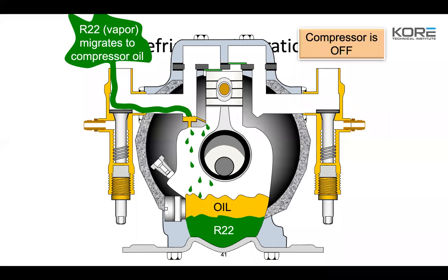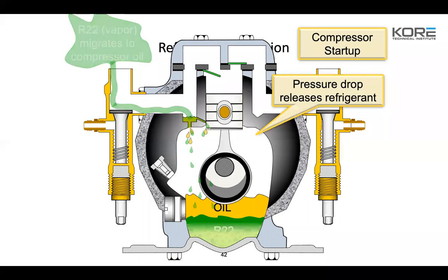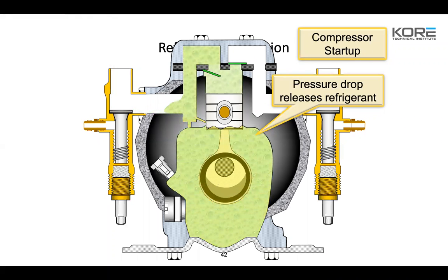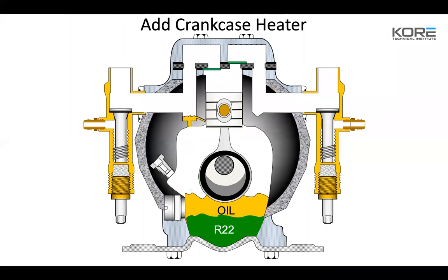I kid you not, I'm not going to tell what market it is because we might have some guys from that market, but it was a warmer climate area. I was out walking the Maverick stores, and I went to 4 stores, and I only had 2 crankcase heaters working of all the equipment in all the locations. It was like 26 crankcase heaters that were burned up. I mean, they were older stores, but it's super important we have those things working. That refrigerant is going to migrate in the off cycle, especially if the unit's outside, into the crankcase.